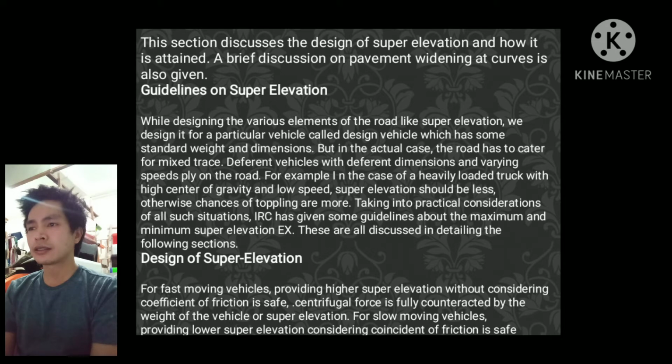Taking into practical consideration all such situations, IRC has given some guidelines about the maximum and minimum super elevation e. They are all discussed in detail in the following sections. Design of super elevation. For fast-moving vehicles, providing higher super elevation without considering the coefficient of friction is safe.